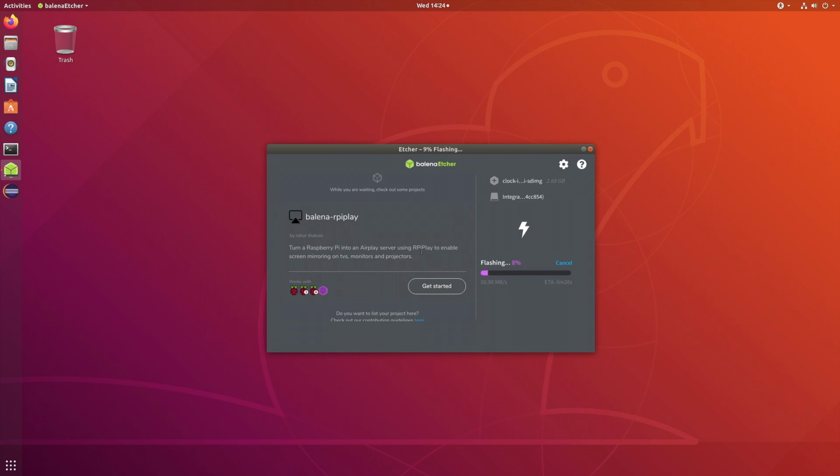It should do that in about 20 seconds or so. Once that is finished, we'll examine what is written onto the micro SD card. Just to reiterate the process, I'm using Balena Etcher to write the contents of the generated Linux image onto the micro SD card, and we'll see what is put on the micro SD card in just about now.